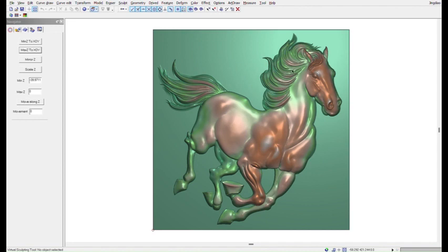And if there is any smoothing needed, in these lines, the contours are making some rapid slopes in the edges of the model. If you are going to carve these rapid slopes in the edges, then the tool will get damaged, so you have to make it smooth.